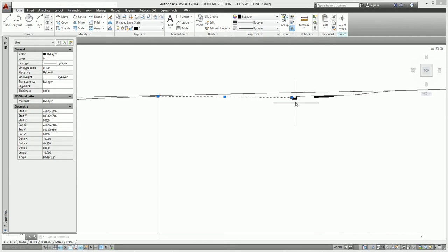And I'm hoping that by just keeping that at 1%, we'll be able to grade around. We'll have 10 metres out at 3% giving us 0.3, and this will give us 0.1, so we're going to have 200 mils of fall hopefully around the cul-de-sac.